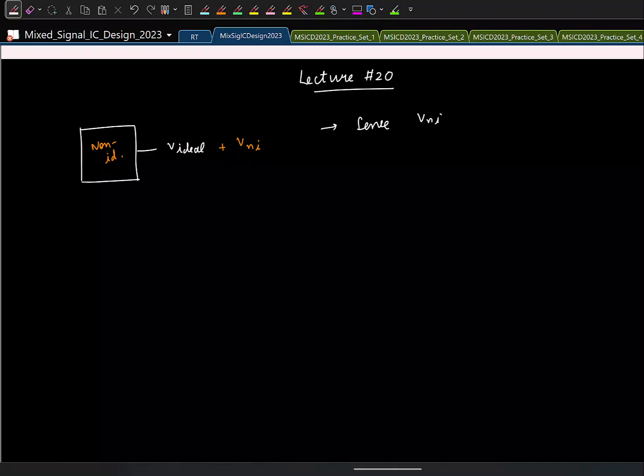And this can be sensed in different ways, and that's what gives rise to different techniques. In the last class, we saw a couple of them. One was where you inject a dither sequence in the form of a pseudo-random noise, and the way we reliably sense the presence of this pseudo-random noise at the output was through correlation, right? So that is one way: dither and correlation.